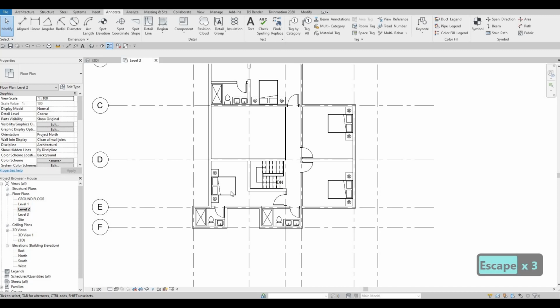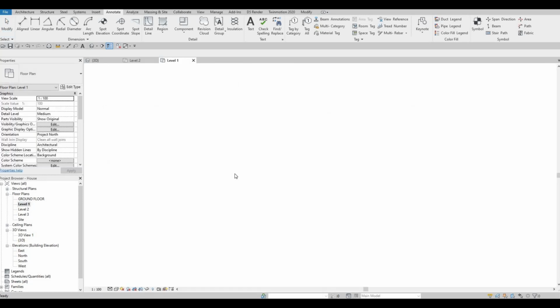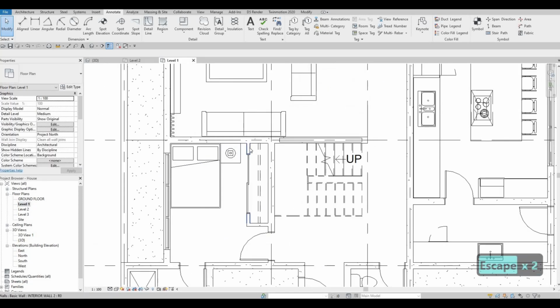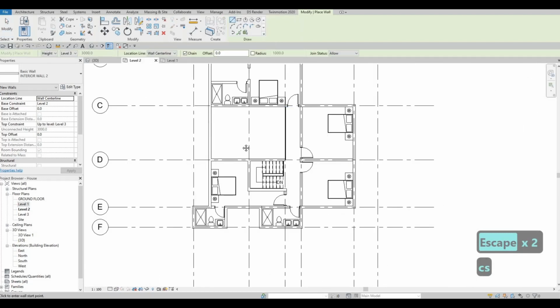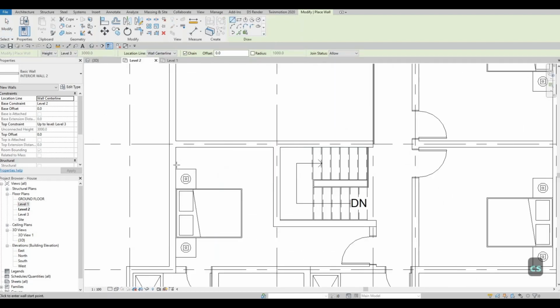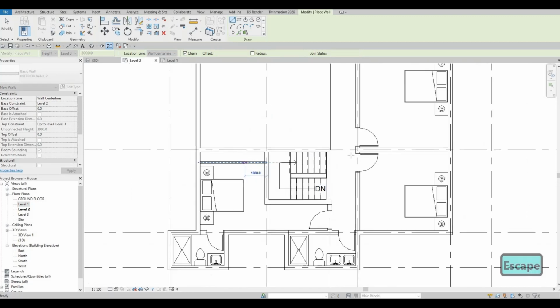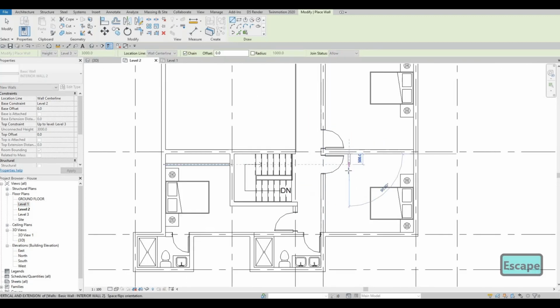And then next thing we're gonna do is we're going to add a closet. So I want to double check if we have, so we have this one right here. So CS on this and go to level 2, and then now we'll be able to add in a closet right here, a closet on this side. So around 700 will be good enough on both sides.